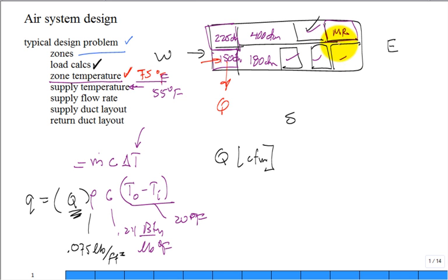You say, what type of ducting do I want? And it's kind of like, remember the reverse return and the direct return on the water piping system network layout? The same thing. Maybe you just say, I'm going to come out with a main duct trunk, come down this way with a main trunk, and then off that main trunk, whoops, that erased some of that. I'm going to dump off a little, bring them off, right? And people like to install flex duct, but if I was you, buying a new house, I wouldn't let them do it. But everybody's doing it. You know what I'm talking about? You ever been up in an attic, looked at flex duct?